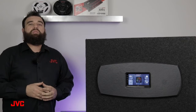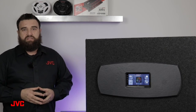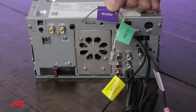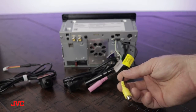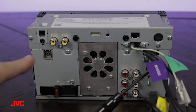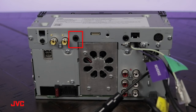So let's turn the receiver around and take a look at all the connections and where everything goes. First, here you'll see you have your reverse input wire. That's what triggers the reverse camera to come on whenever your vehicle is in reverse. Here you'll see the connection for the front view camera, and here's our rear camera input, and the final camera input is shared with the AV in. Here you can assign the AV in to a camera input and utilize it as your third camera in.